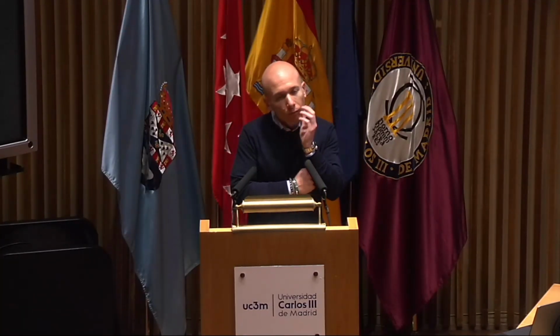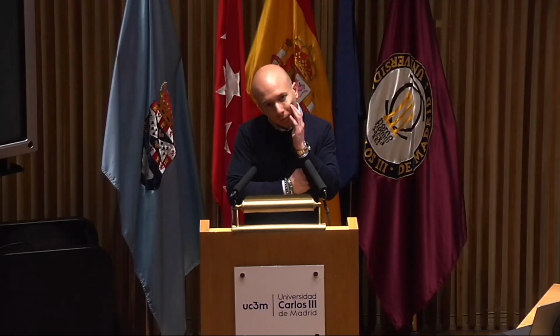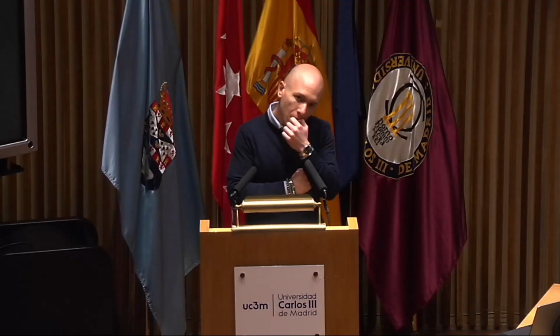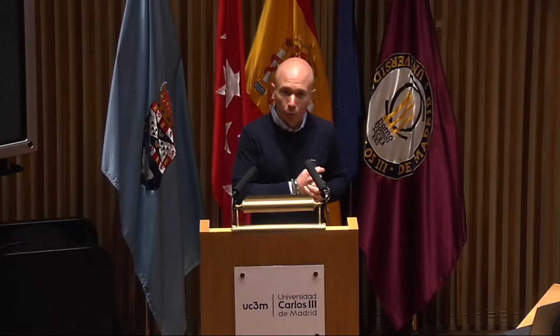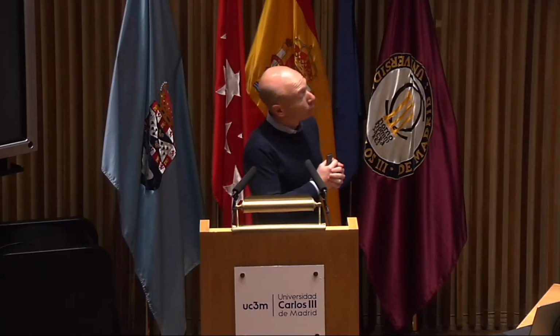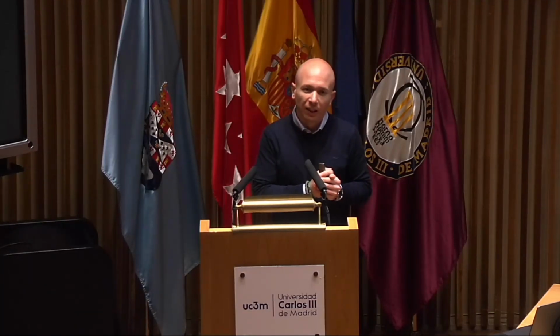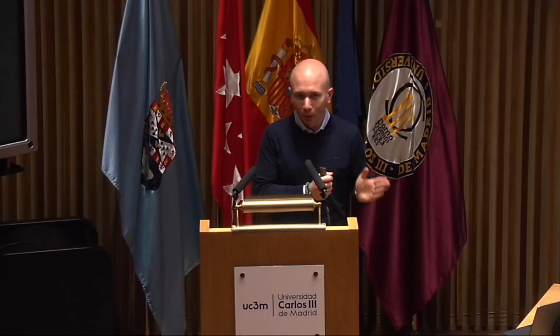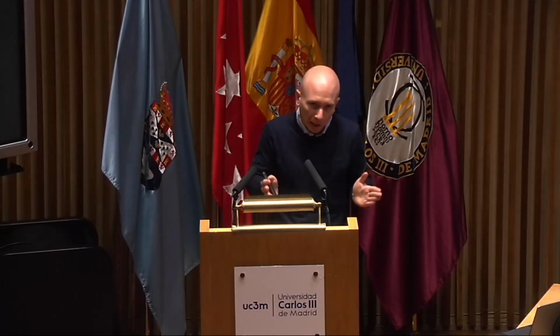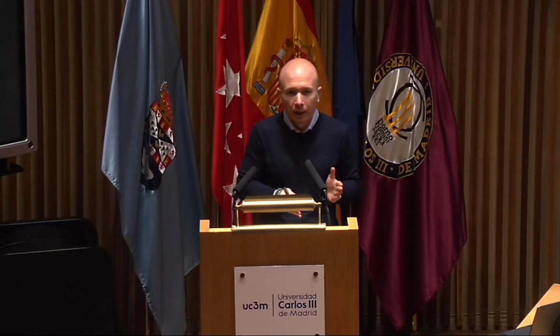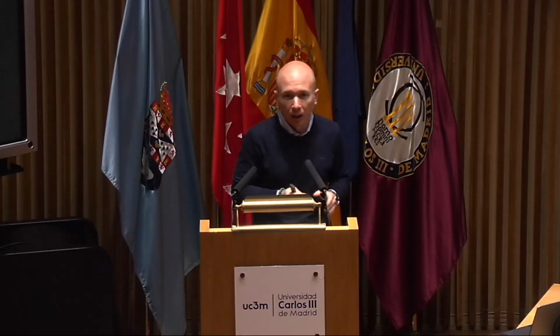Okay, and also related to that, how are you performing your simulations? The flow is turbulent, the flow is not turbulent? The flow is fully turbulent. I forgot to mention, sorry. We are forcing the flow with a physical trip, a kind of zigzag trip, at a certain point, such as to have in my computational domain more or less the same boundary layer as in the experiment at the beginning of the liner.